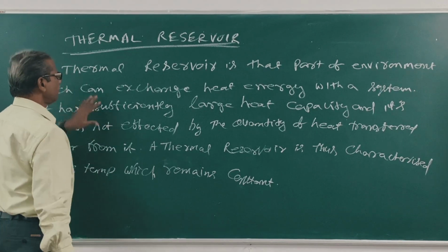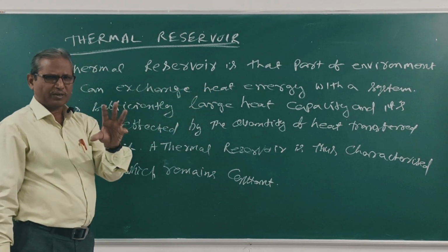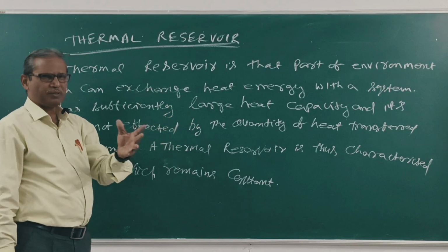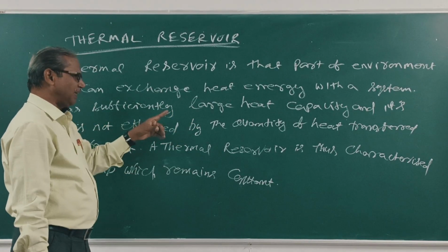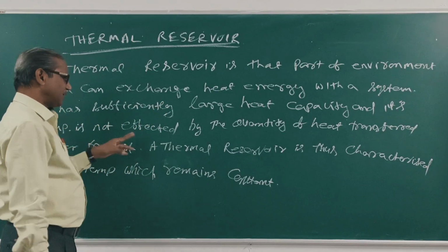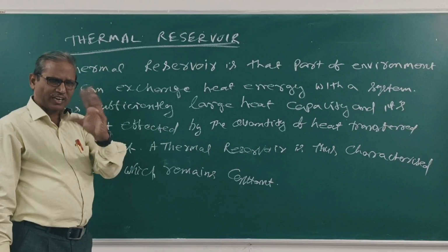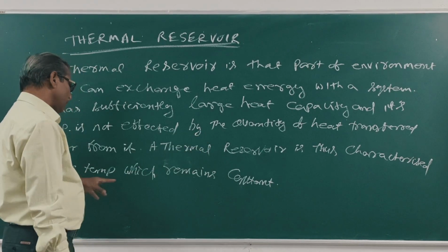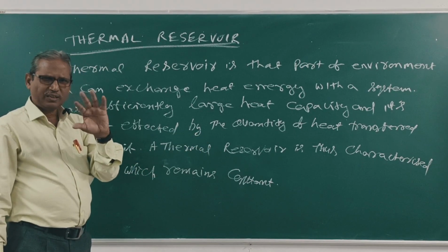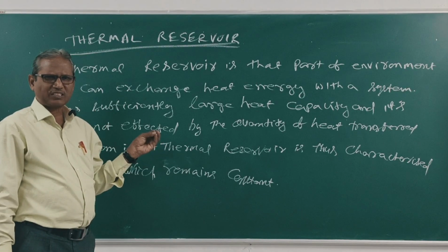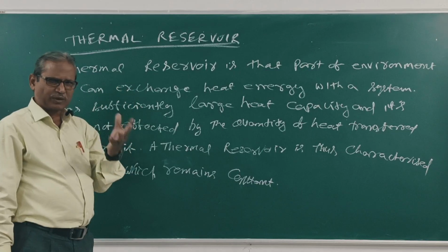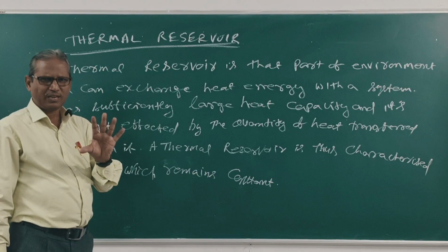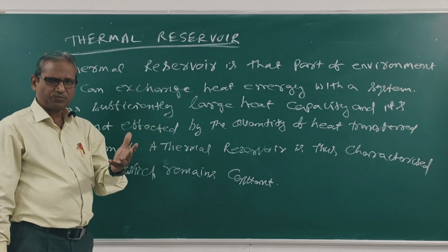Now, a thermal reservoir is that part of the environment which can exchange heat energy with the system. Clear? It has sufficiently large heat capacity and its temperature is not affected by the quantity of heat transferred to or from it. Clear? It is characterized by a temperature which remains constant. The heat transfer is very slow, so this is quasi-static. Clear? So when heat is transferred to or from the reservoir, it will not affect its temperature. Then I will discuss what is a source and what is a sink.